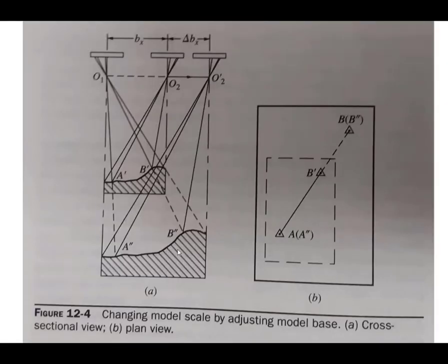If you want to determine an accurate volume of a gravel stockpile, if you're not interested in the location of the gravel stockpile, you're not interested in heights or elevations of points on the stockpile, do we really need to go out and set GCPs and then use our RTN or RTK or total stations to put 3D positions on the ground control points?